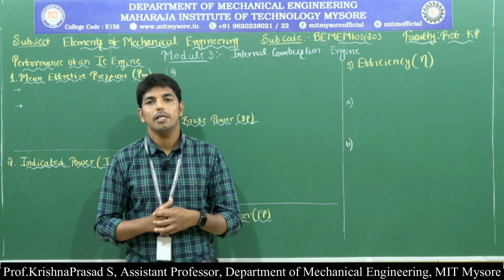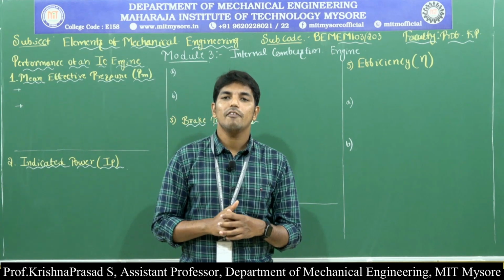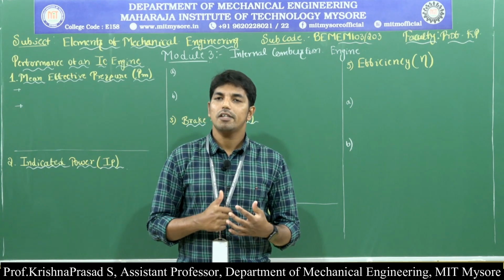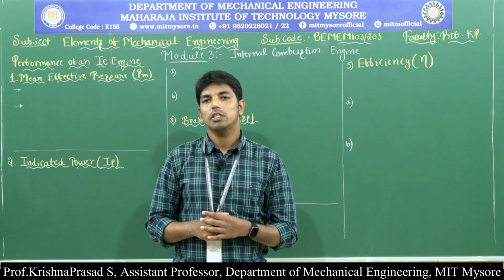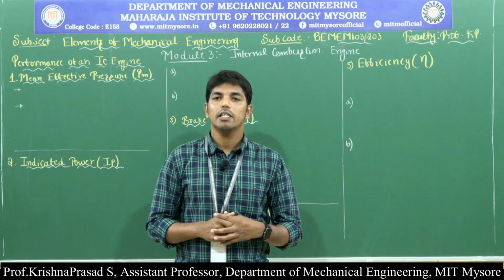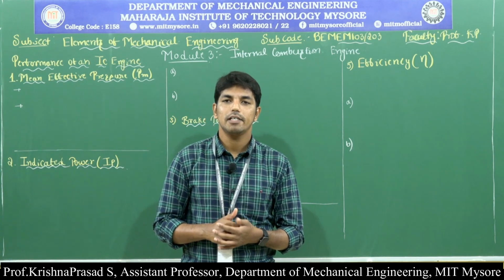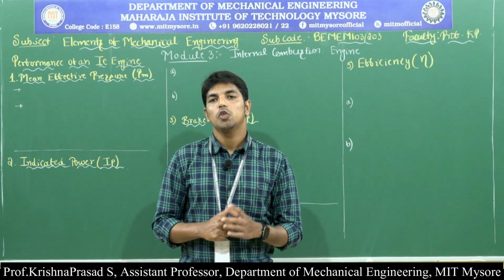What is meant by the mean effective pressure? The mean effective pressure is the mean or average pressure acting on the piston during the power stroke. We have already studied the working of the 4-stroke engine. In the 4-stroke engine, in order to complete one working cycle, the piston has to perform 4 different strokes like suction, compression, power and exhaust, and the crankshaft has to revolve 2 times.